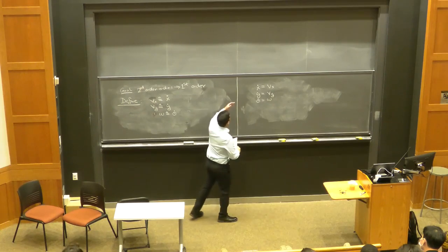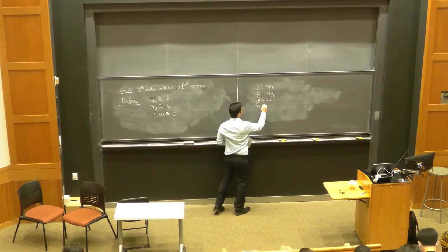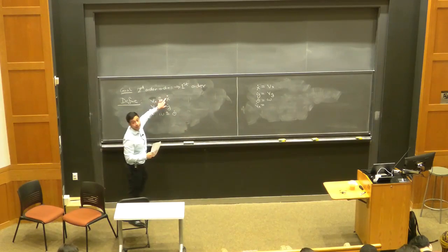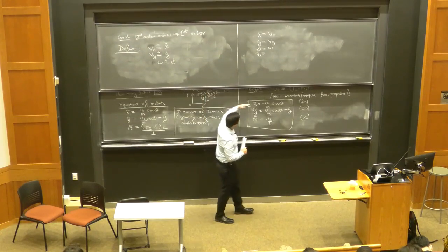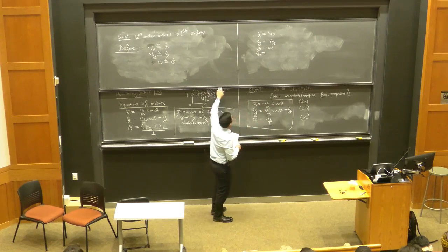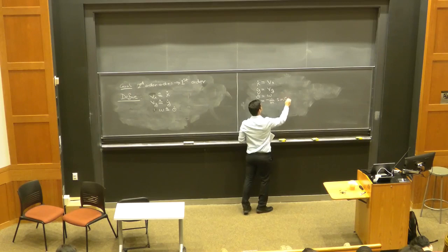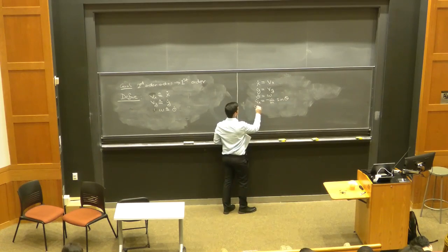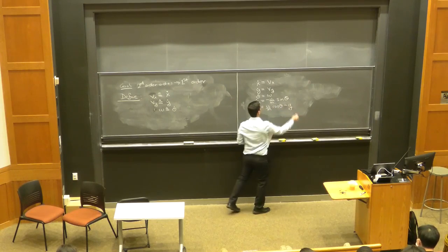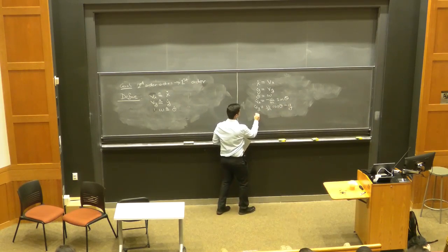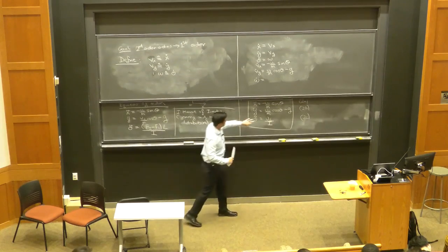The more interesting ones are when we look at the time derivatives of these new variables that we introduced. So Vx dot, by definition, is x double dot, right? Vx is x dot, Vx dot is x double dot. So we can look at this differential equation: x double dot is minus u1 over m sine theta. So Vx dot is minus u1 over m sine theta. Vy dot is u1 over m cosine theta minus g. And then finally omega dot, which by definition is theta double dot. We can look at this last equation. It's just u2 divided by I.